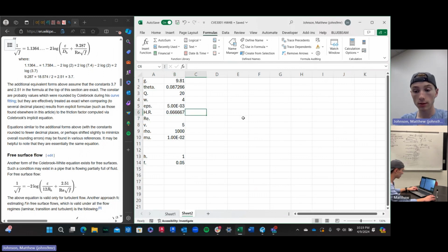That's right. So, I'm not sure if I said this, the hydraulic radius happens to be equal to half the radius of a cylindrical pipe, or 1/4 of the diameter. So that's how we can get the Reynolds number here.